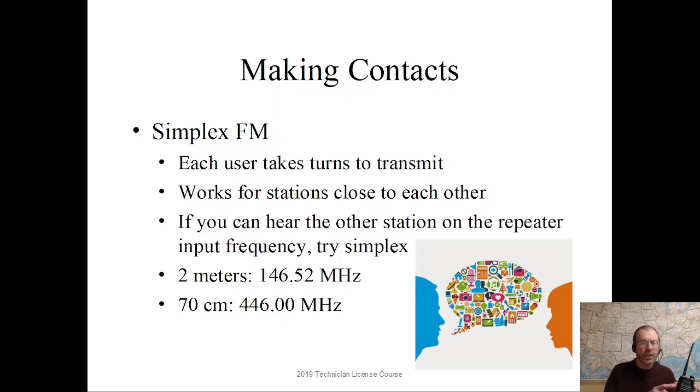And in fact, you can set the power down to maybe 1 watt, so you can save your battery when you're transmitting, and you're very close by, so simplex frequencies work great for that. Our two simplex calling frequencies here are 146.52 megahertz and on 70 centimeters 446.00 megahertz in the band plan.